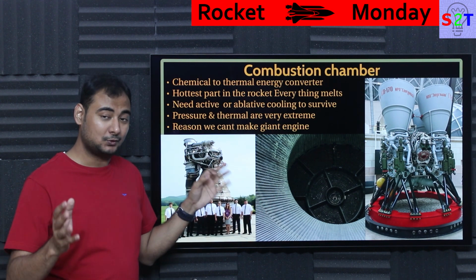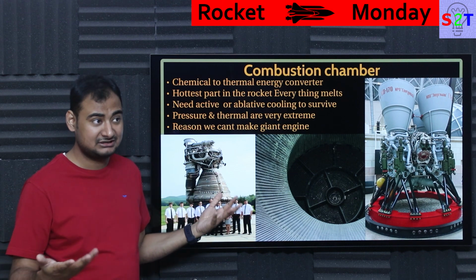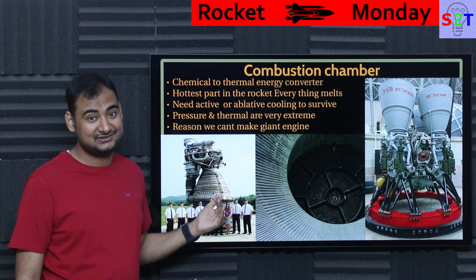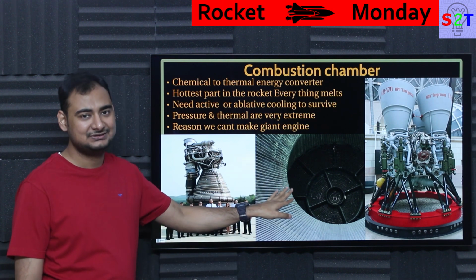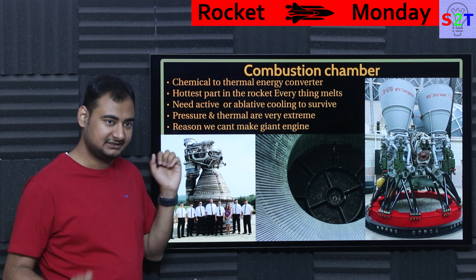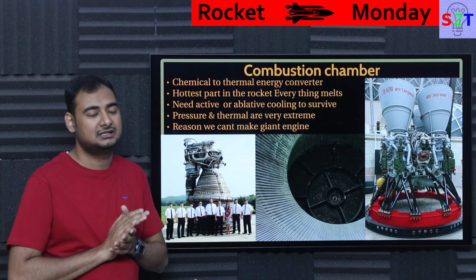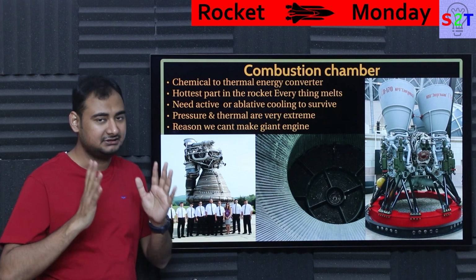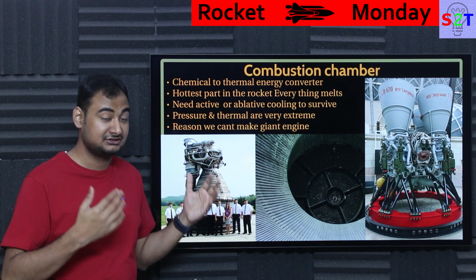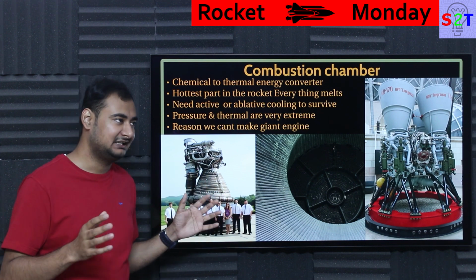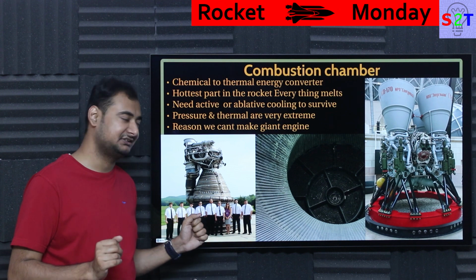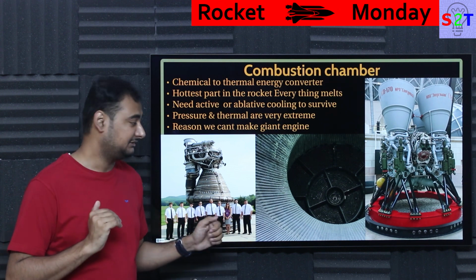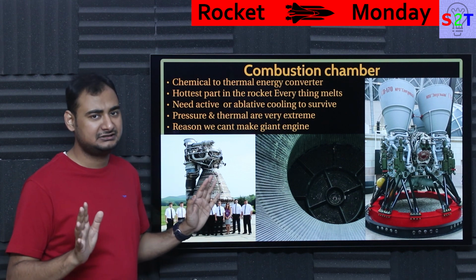And again, pouring liquid oxygen there may sound awesome because it's cold, but the problem is it's reactive. Kerosene is not reactive, so that's why you want to flood it with fuel. The same is done in the RS-25 space shuttle engines. They are using hydrogen. Hydrogen is not reactive, inherently not as reactive as oxygen. Oxygen puts way too much stress on metal, so they generally prefer not to flood it with oxygen. And in the case of Raptor, they are using methane to flood it, which you rarely hear about. Again, it can be done.